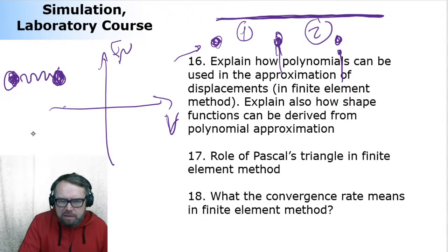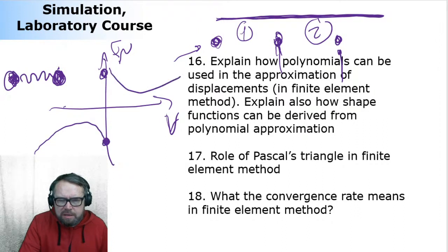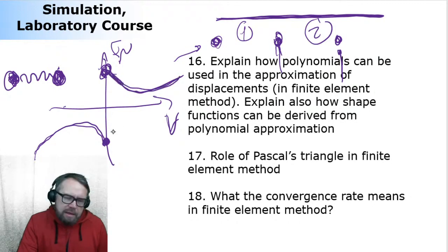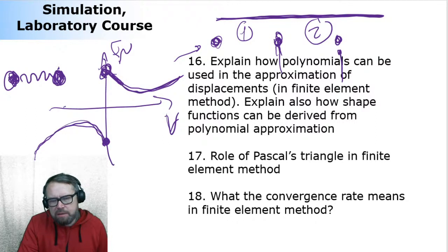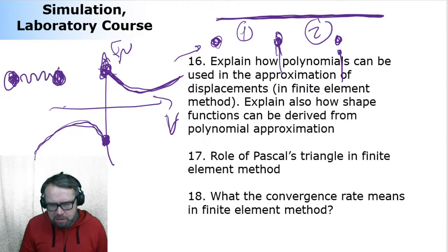The friction behaves in such a way that there's a discontinuity at this point. The friction curve is capable of describing the stick-slip phenomenon, as the curve here has a negative slope. And when there's a jump, these jumps are poison to computing and to simulation in general. So you want to avoid discontinuities as much as possible, because a jump is going to be very, very hard to deal with.